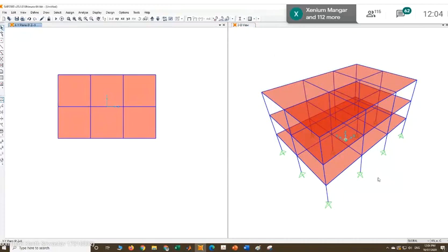Now one additional thing to check is the base of the building. We know that the building rests on soil, so we need to actually define soil properties also. But in practical purposes, we need to design buildings in quick succession, and there are lots of things we need to learn for soil. In conventional design for simple residential buildings of 5 to 10 stories, soil properties are generally not considered for modeling a building.